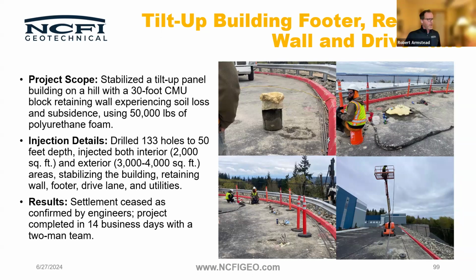So what methods do you use to estimate how much material to use per pipe per area? I would say per injection location. How much chemical? Yeah. Okay, yeah. I mean, a good rule of thumb, at least in my area that we found was between 30 and 70 pounds per injection level. But that's going to vary greatly depending on your depth.